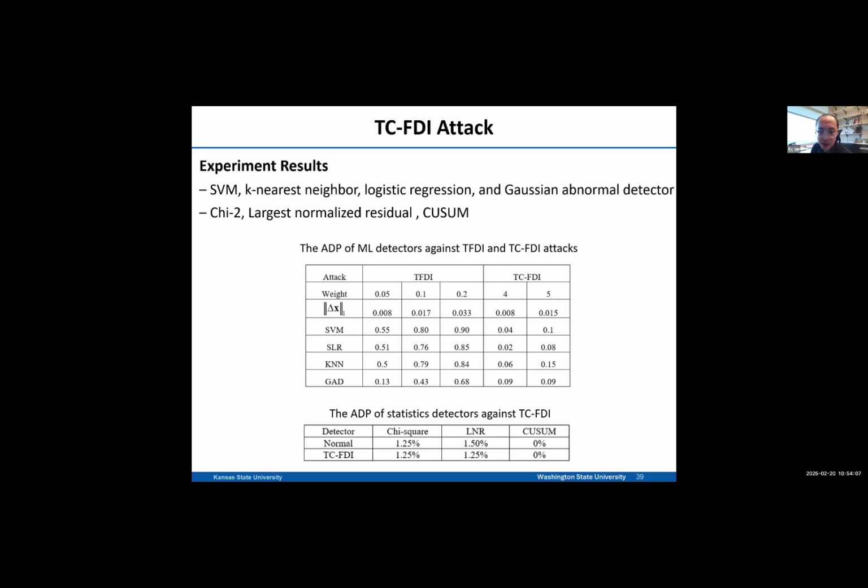If the system operator uses protected sensors with a good strategy, then the attacker cannot launch the proposed low rank attack. The second attack assumption is that the attacker needs accurate topology or line impedance, so if the operator applies the moving target defense and changes the line impedance, the proposed attack will use the incorrect line impedance, and the attack will be detected by the data detector. That's all for my presentation.